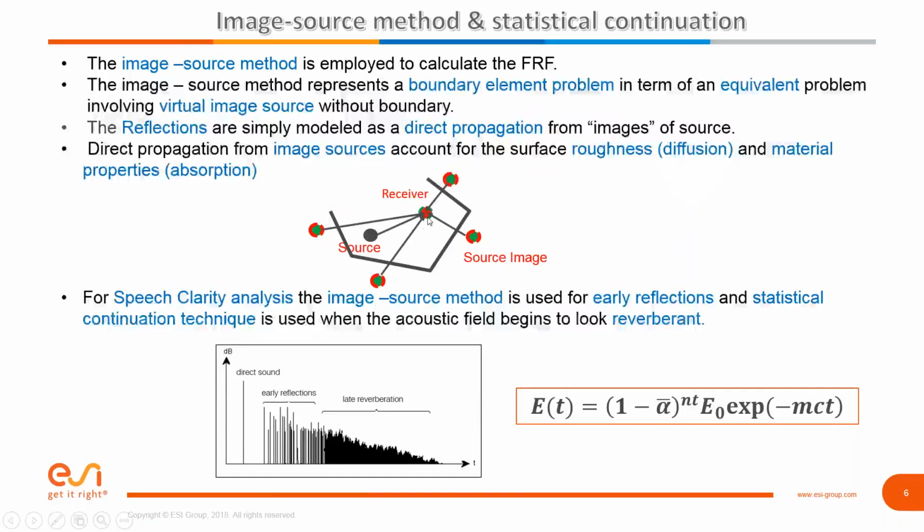They can be points, individual sensors. They can also be data recovery surfaces, entire faces, and that's a nice advantage versus real physical test. You'll see in a little bit, if we use a face, we can have a lot of detailed, fine, accurate information about the character of an acoustic field, which is hard to get from test.